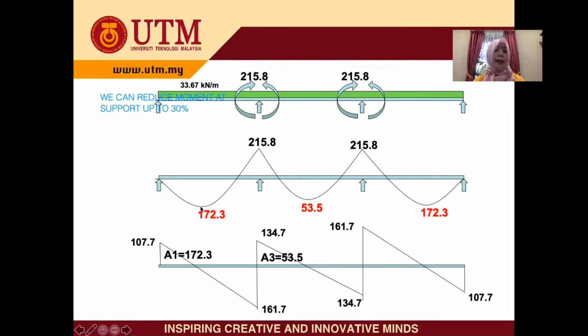Meaning that, have you heard about the plastic hinge? Plastic hinge will occur here, while here is not yet. So therefore in design we hope that both of them will reach plastic limit, and the hinge will form about the same time. Here we will get plastic hinge here and also here.